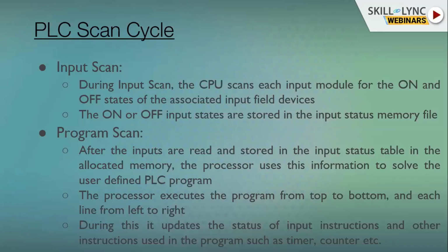In most PLC programming, one end line is inserted in the PLC program automatically, to identify that the PLC program is over. Once it reaches that end line, it will jump again to the top line and start again from left to right, executing the PLC program.